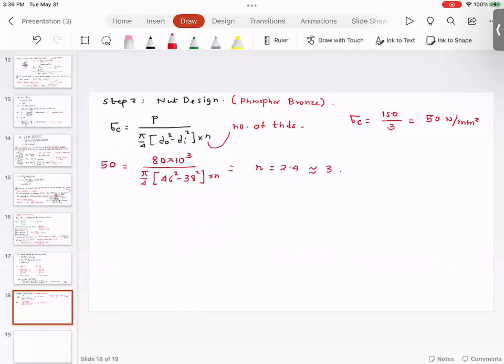So you always have to compensate for some clearances, some partial threads, and some alignment threads. So even though from this design you just need 3 threads in contact, from an alignment and clearance point of view, you need to add additional threads to this assembly.